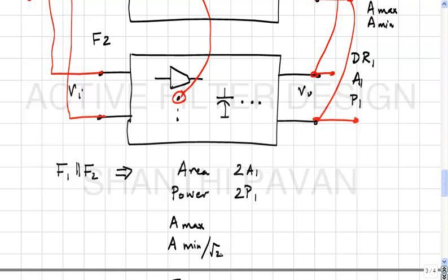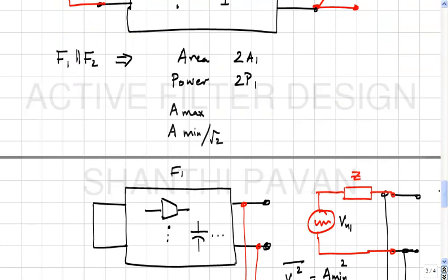So why is it brought in? Vn1 and Vn2 are completely independent, right? Because they are happening in two different networks. So if I multiply them, it's also important to note that Vn1 and Vn2 are zero mean. If they are not zero mean, then I would just give up this job and go build a filter, tap that energy and supply it to the grid, and then we'd all be very happy. You understand? So all these are zero mean processes, and uncorrelated with each other. So when you multiply them and average them, the result must be 0.